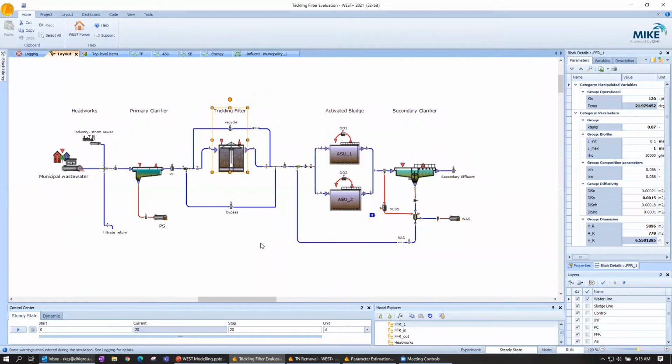A lot of times I'll build a model and then realize, wait a second, we actually don't know how solids are controlled at the plant. How often is an operator actually looking at this mixed liquor suspended solids concentration and adjusting wasting rate? Is it automated? Is it a daily or weekly check? Is there even a VFD on this pump or valve? How can it be controlled in practice? And then how's the return sludge controlled? Things like that. The calibration phase uncovers these missing pieces that you didn't know you didn't know.